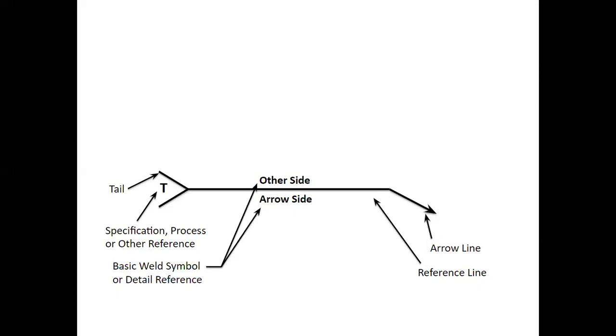The way I use this is I look at which of these here. So if I was drawing that field weld symbol, I do that circle here, the smaller of the two circle pieces. So this would be a bigger one encompassing what? I don't know, 200 plus degrees, and this would be a smaller one, say 160 degrees, right? The smaller one is always going to be the arrow side. So that's how I remember that.